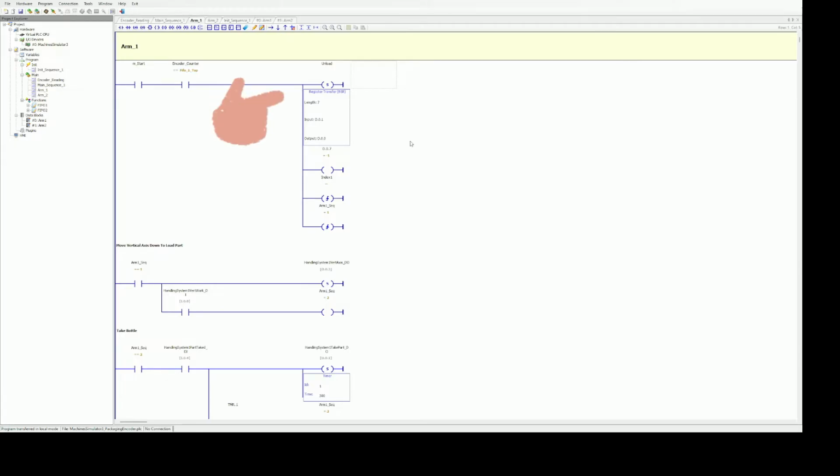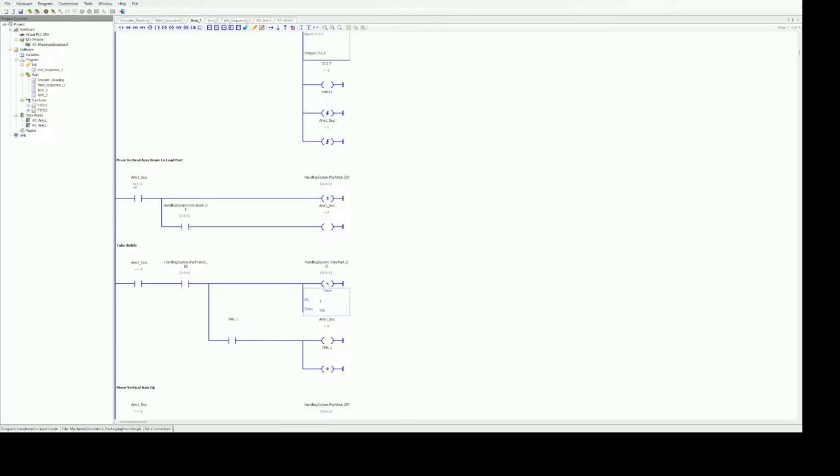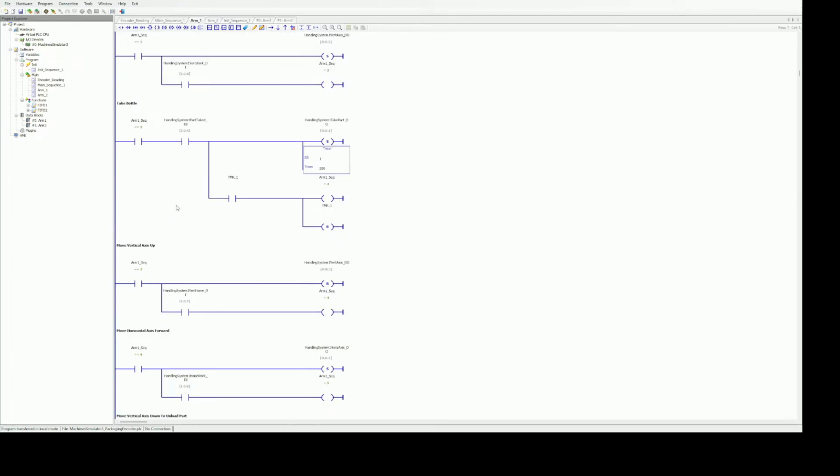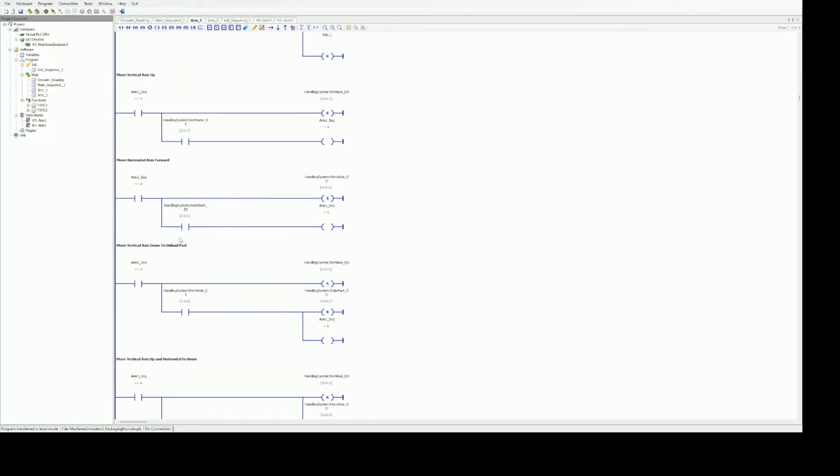We use the register transfer command to run a position in the stack, and thus we update the values so that the stack works in FIFO mode. We reset the last value of the stack. We subtract 1 unit from the index that calculates the pointer to where the stack points to be filled again. And we activate the sequence so that the arm begins to move and unloads the blue bottle on the starting line. Below is shown the graphic or sequence of 6 steps to move the robotic arm and deposit the bottle on the output line.